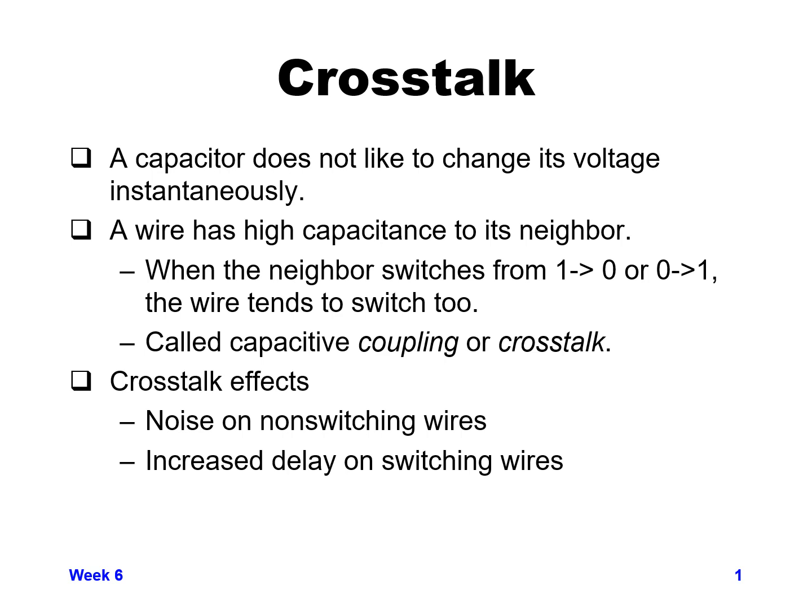So the two main effects of crosstalk are, one, you'll get noise on wires that are supposed to be stable at a given time, and that could induce noise in the downstream logic receiving this wire, which might cause that noise to be propagated down a logic cone and cause an incorrect value to be captured in a latch or a flop.